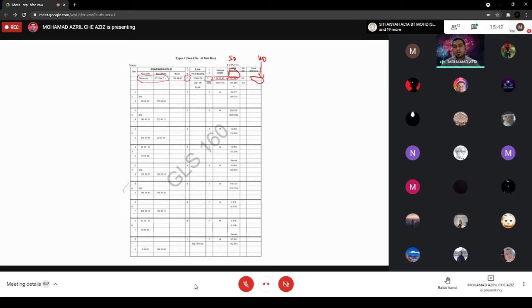That's why I want all the students to look. I think in the tutorial class or practical class before this I already showed, but I show again, so at least you know how to record. 2 to 1, you will set as your reference, and then 2 to 3 you will observe. Here you fill up this value: 189, 44, and 40. And then for the face right.